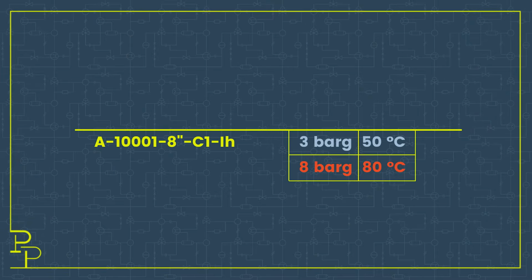Another thing I forgot to do, which is quite common, is to put a little 2x2 block onto the line to show firstly the operating temperature and pressure, and then the design temperature and pressure. The operating temperature and pressure is what you expect as a maximum on your PFD.